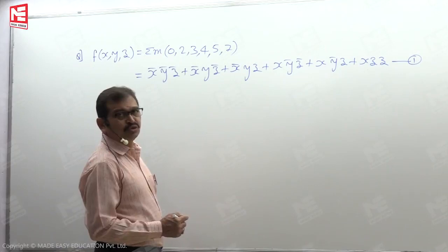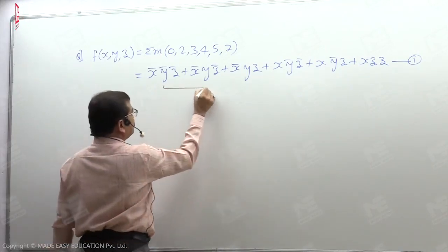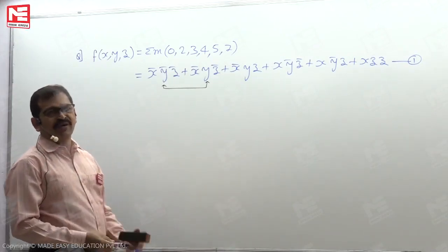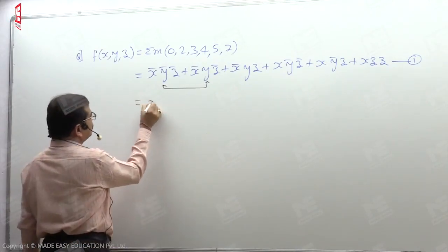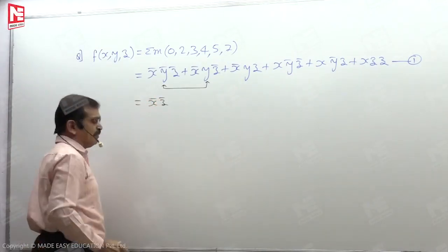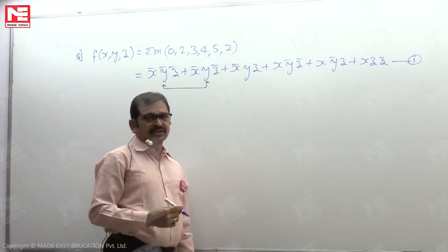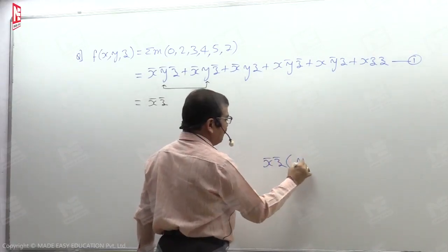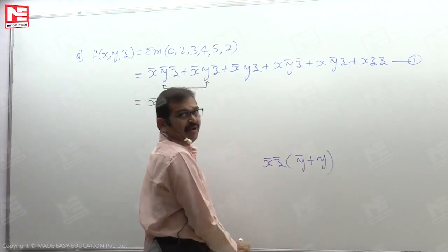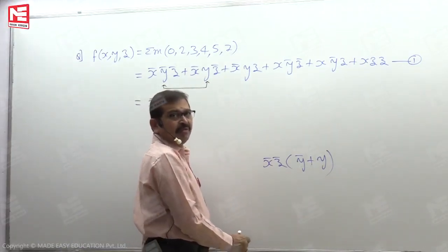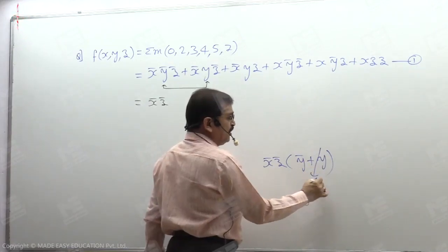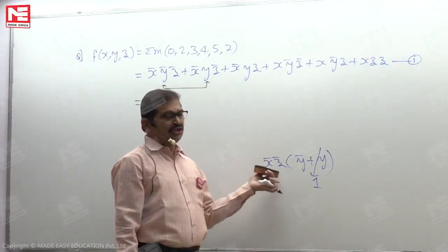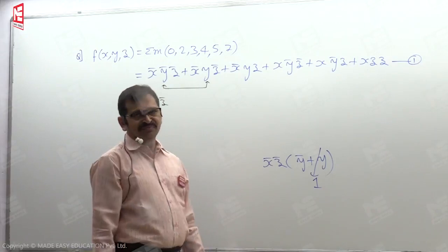We have the possibility to group the first two terms. From grouping the first two terms, the product we get is X complement, Z complement, because from the first two product terms, X complement, Z complement is common. Then within the parenthesis, it is Y complement or with Y. When it is Y complement or with Y, using the Boolean algebra fourth property, it is 1. And using the second property, 1 and with anything is anything, so it is X complement, Z complement.